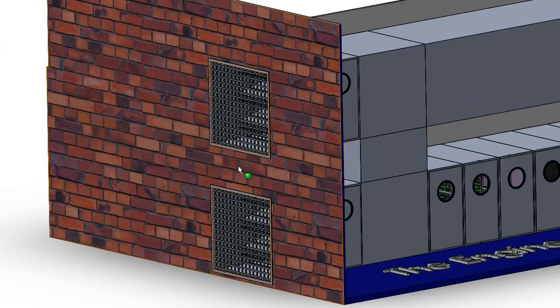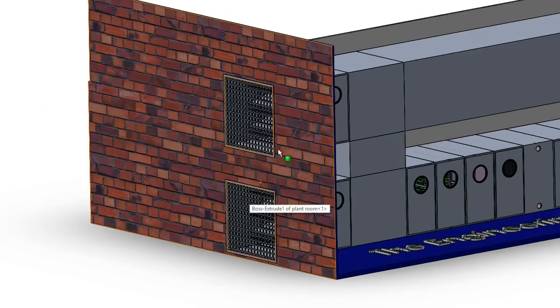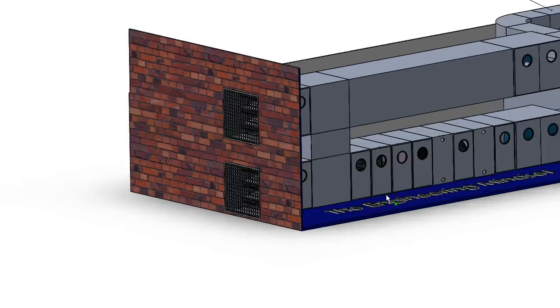It's obviously important not to have these two ducts too close together, because you'll just get recirculation. So ideally these would not be positioned so close, but for an example, so you can see how this is working, I've left it so close. But in the real world, do not do this. Don't put it as close as that.